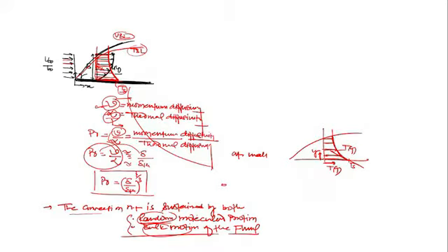So at the wall, at y equal to 0, at y equal to 0 plus means near the surface. You can also write y equal to 0 in general. Near the surface, heat transfer through conduction is taking place. The heat flux by conduction, q dot conduction, small q means flux, is equal to minus k, k of what, solid or fluid? Is conduction taking place in the fluid or the solid? In the fluid only, because the solid is already isothermal.